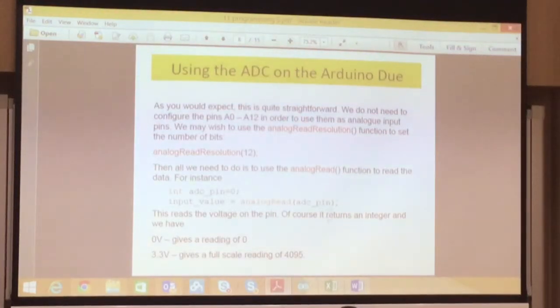Okay. Then next, because we want to take the analog reading, first we need to define our analog read resolution. Here you have two options actually. You can define it as 10-bit or 12-bit analog inputs. This basically is the resolution we have discussed for the ADC.